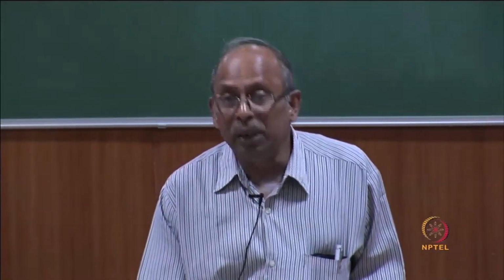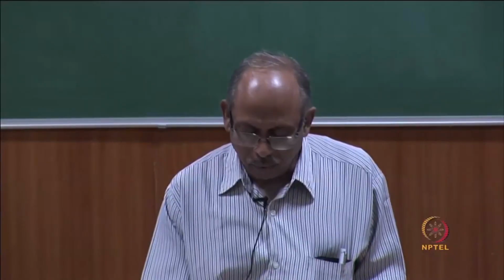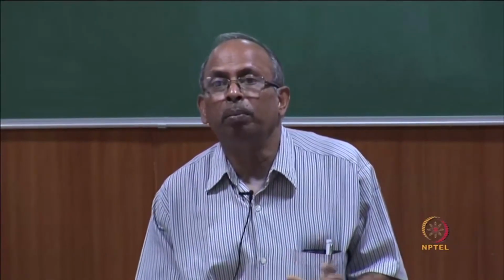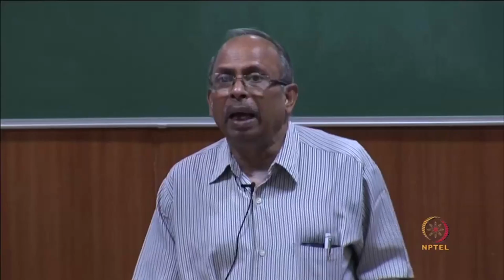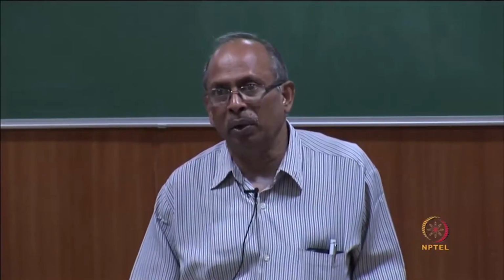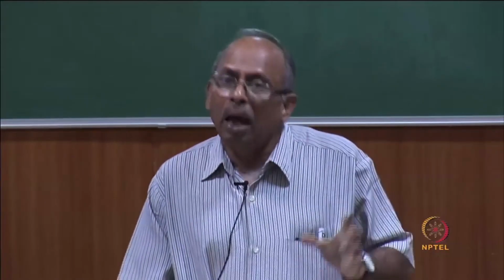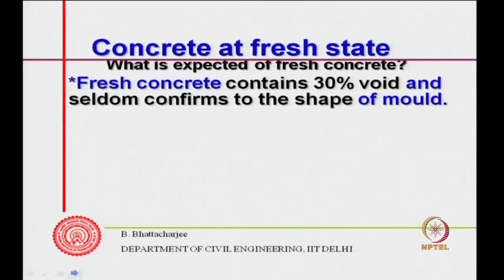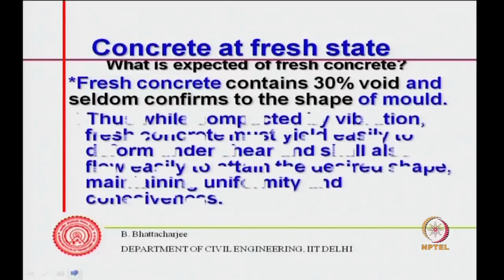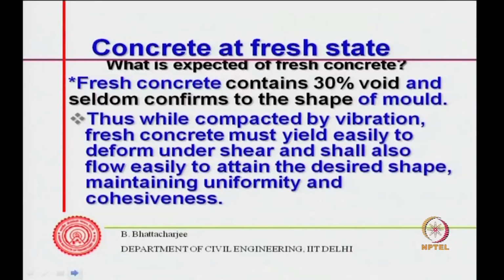So, this is one issue, of how much paste you need to have properly compacted concrete. But the other issue related to this is the consistency of the paste itself. To look at that, we should look at what is expected of the fresh concrete. Normally, I am talking again of normal concrete, it will contain around 30% void, and it does not conform to the shape of the mold. So, therefore, we compact it by vibration, and when you are compacting with vibration, it stands in a heap.